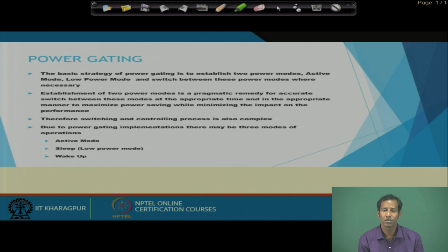So, if you can reduce this leakage power, that helps. Nowadays laptops and phones are like that. If you are not using them, after a certain period of time, let us say 10 seconds or 1 minute, the laptop or phone goes into idle mode, the display is shut down, and some of the processing blocks also get shut down. Why? Because whenever they are not in use, why supply the power to each of these modules?